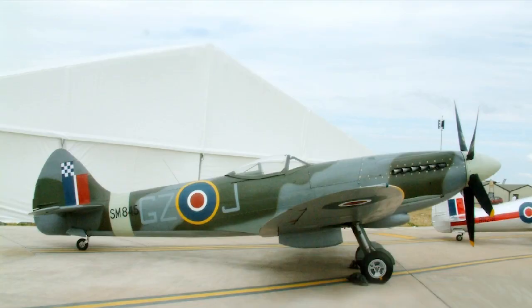Most engines which are fitted with a supercharger will also be fitted with a variable pitch propeller. This will be controlled by a constant speed unit. The RPM of the engine is therefore controlled by the propeller pitch lever. To accurately set the power and also prevent the engine from being overboosted, the pilot must have some indication of the amount of pressure he is allowing into the engine.